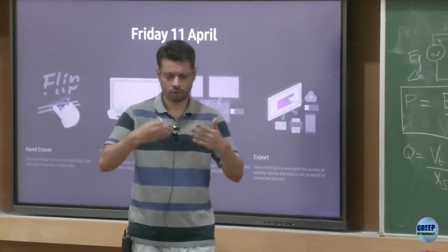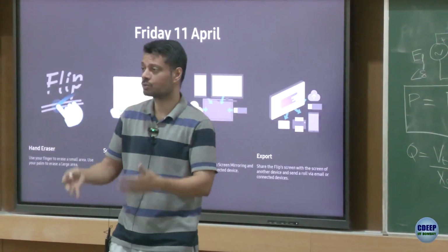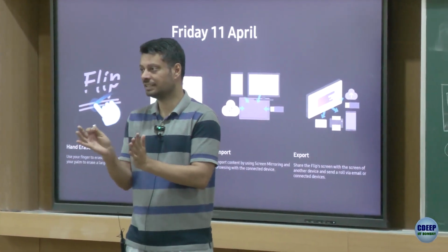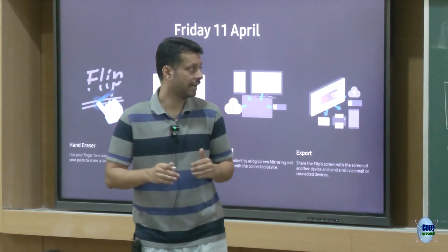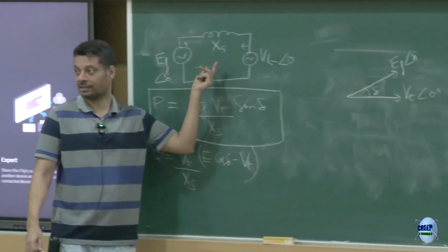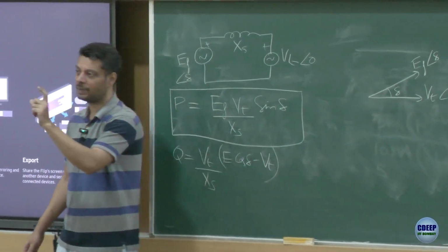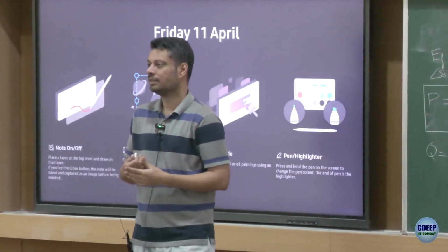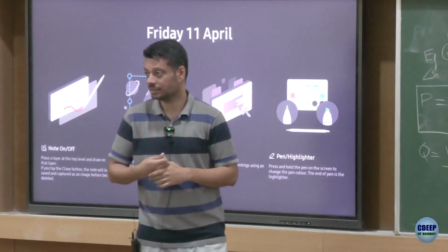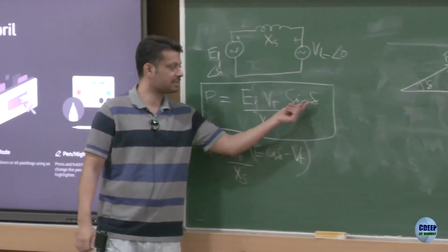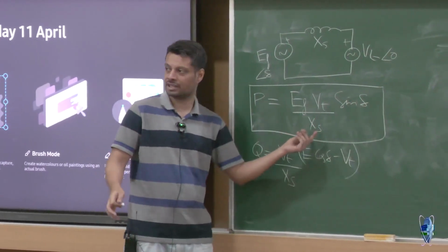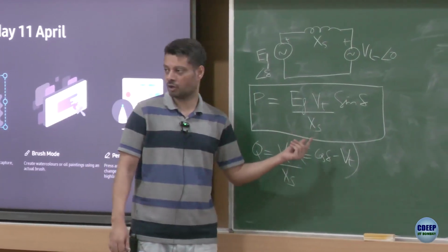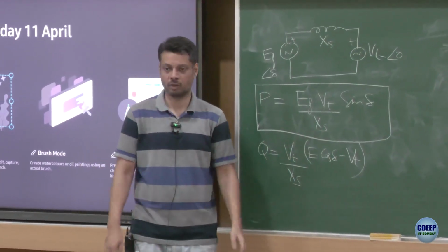Yeah, so as you will see later on in more advanced courses, 90 degrees is too dangerous, because once you go on the right side of the 90 degrees, everything changes. So usually you try to keep delta such that you operate within a small band, let us say plus minus 20 degrees maximum, if not less than that. You do not go into extreme cases of 90 degrees, right. So you can have 10 degrees, 15 degrees, you can tune it accordingly. So you will achieve the rated power flow. You have to keep delta small also, which we anyways want to do.